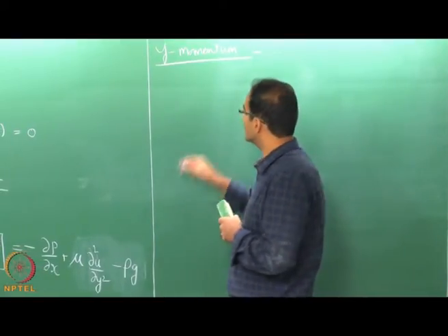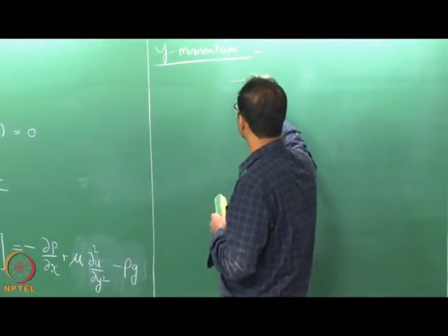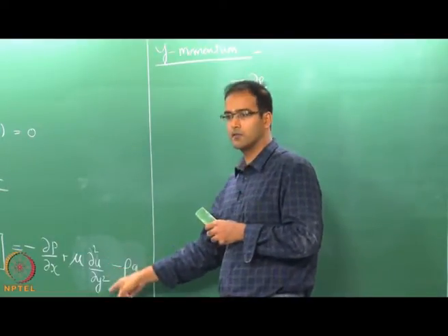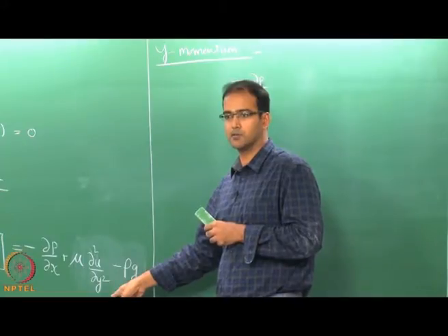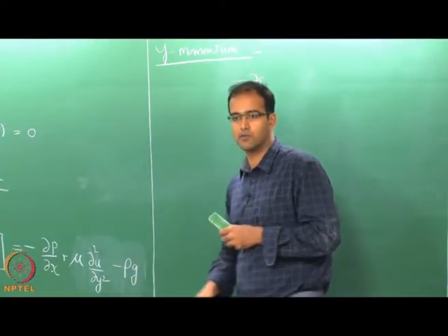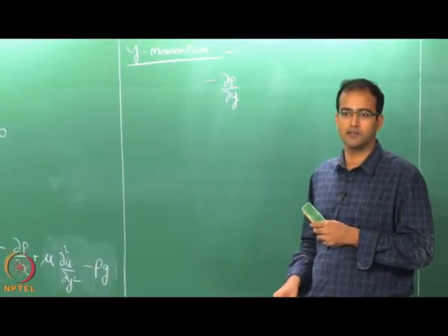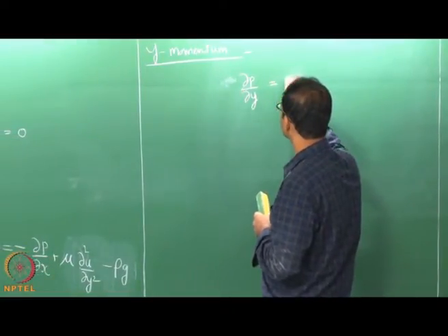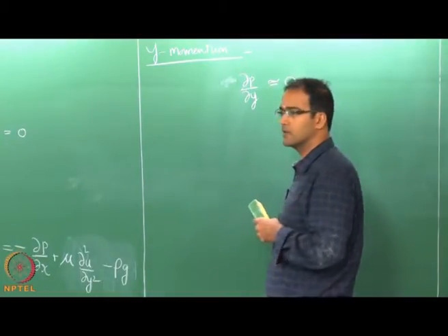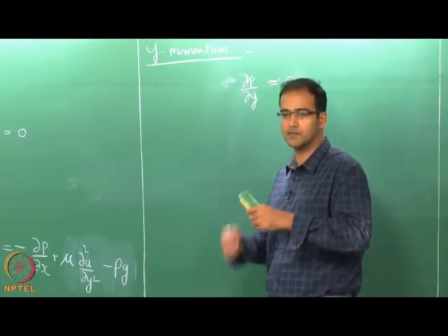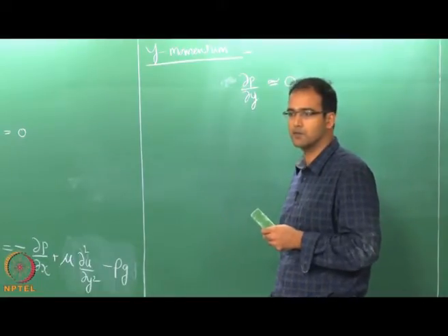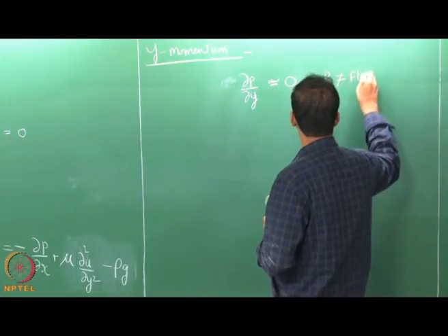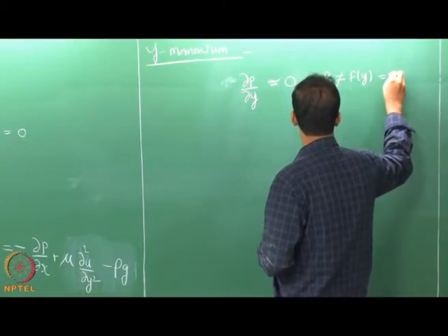On the right hand side, you will have the pressure gradient term dp/dy. There is no diffusion of the v momentum also, and there is no body force in the y direction. So, essentially dp/dy is approximately 0, very small, the others are very small. So, we can approximate it to 0. That means p is not a function of y, that means p is a constant along y.